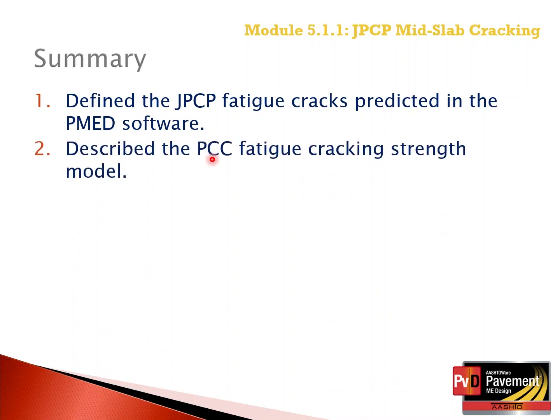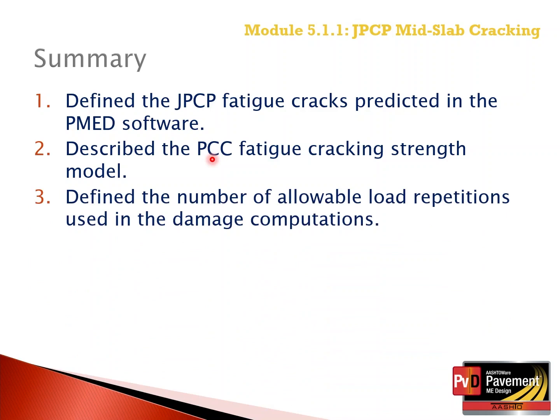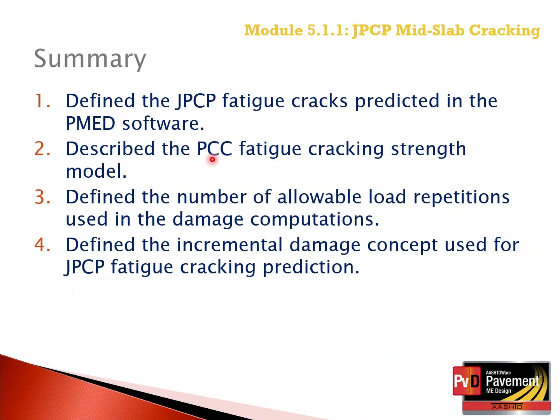We described the PCC fatigue strength relationship included in the PMED software. We define the number of allowable load applications that are used to compute the fatigue damage for a specific condition. We define the incremental damage concept used to predict percent cracked slabs of jointed plain concrete pavements relative to Miner's hypothesis.